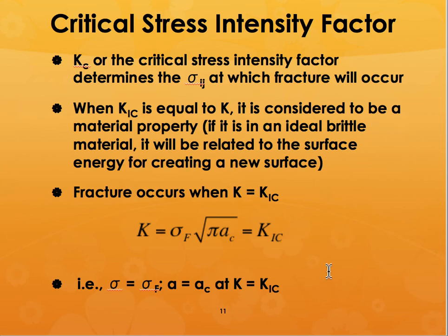And that has been derived to be equal to the failure stress times under root pi times the critical flaw size, which is equal to K1C. Which means that at the critical stress intensity factor, the flaw size will be equal to the critical flaw size and the stress will be equal to the failure stress.